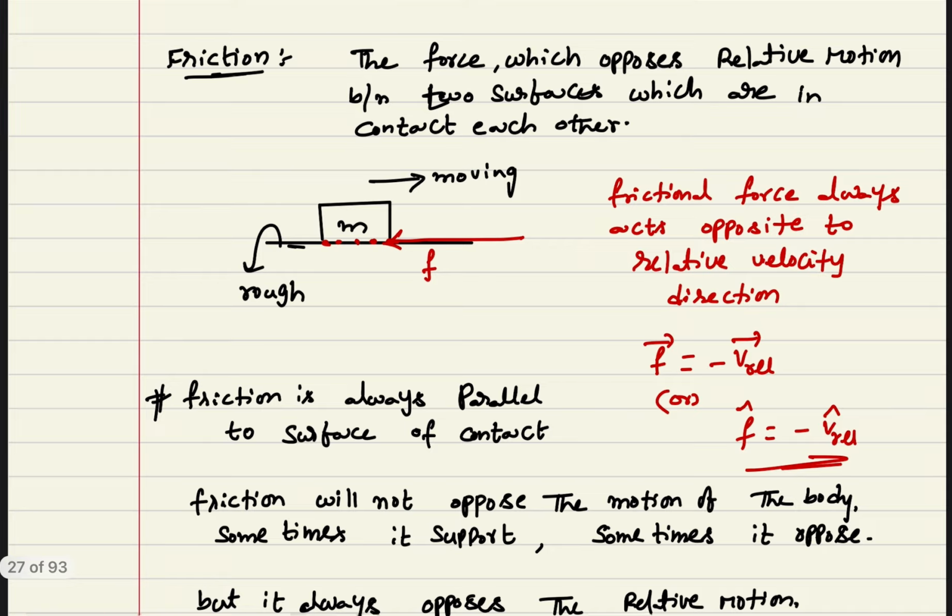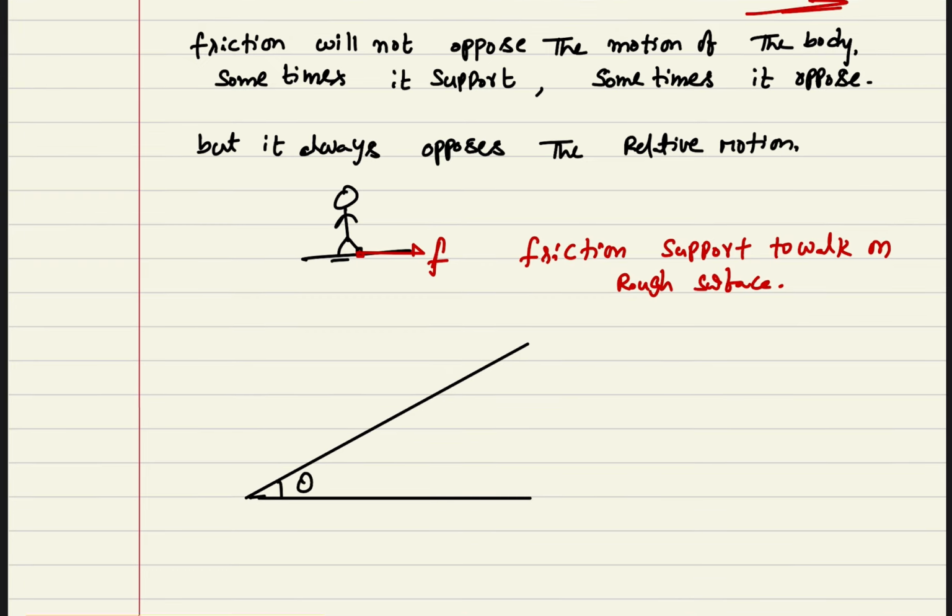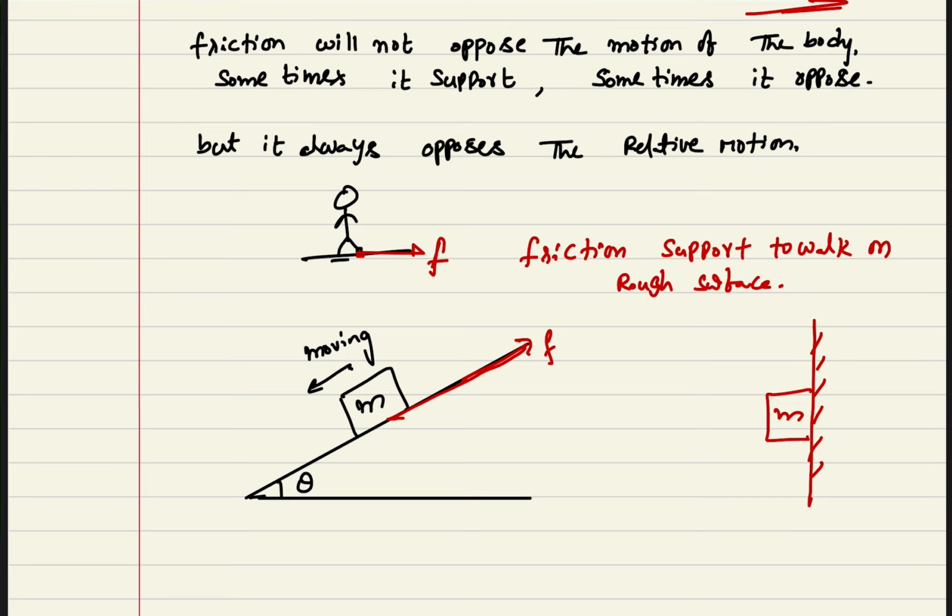Now this is about the friction. More details about the friction we will discuss in the later case also. But I am drawing the free body diagram, how the free body diagram of friction will be. In one case, a mass m is located, a body is moving. In that case, frictional force will be acting like this. Suppose a body is placed against this wall, someone is pressing this, and the body is about to move downward. In that case friction is acting in the upward direction.